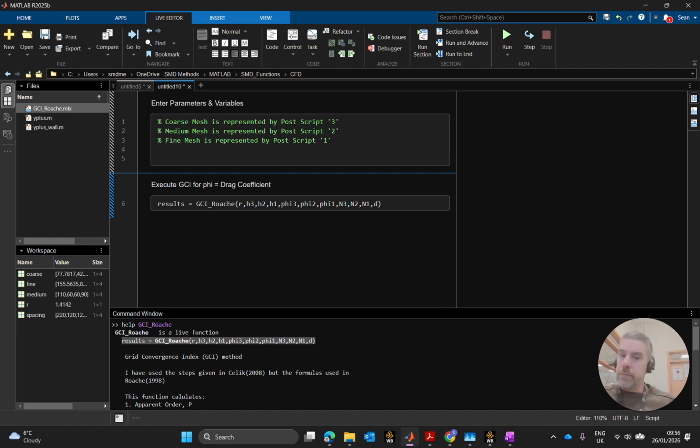That is a must. We also must make sure that from mesh to mesh, from refinement to refinement, our difference in our variable of interest, in this case drag coefficient, gets smaller and smaller and smaller. Drag will be good because it is dominated really by skin friction on the airfoil surface. So the skin friction, very momentum based, which is great. It will behave very well, where drag and lift will behave for our mesh up till a certain state, I think.